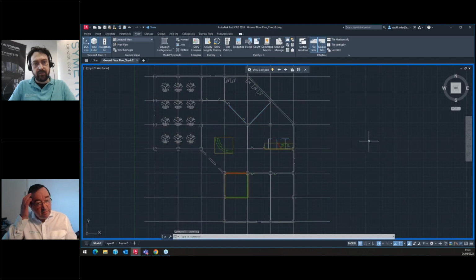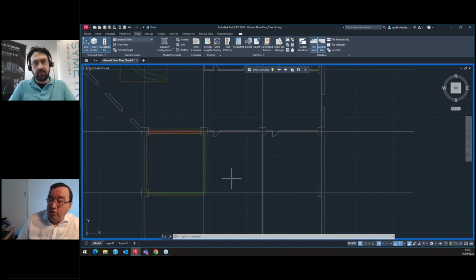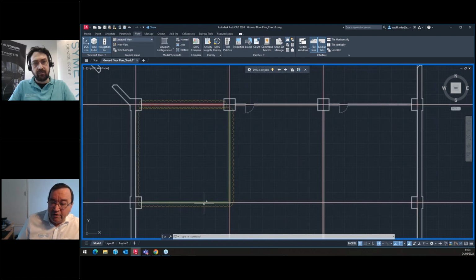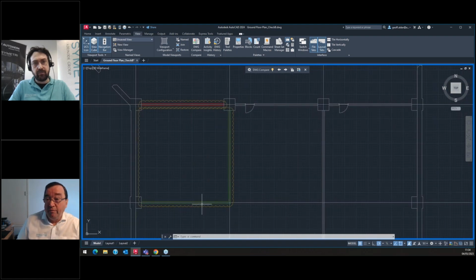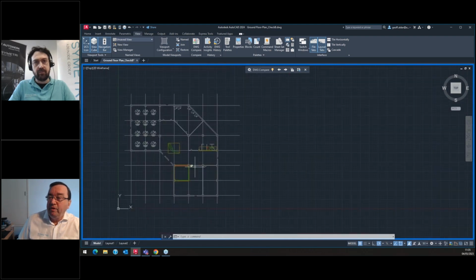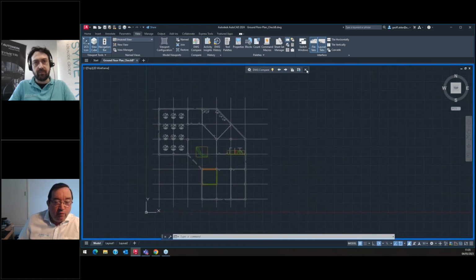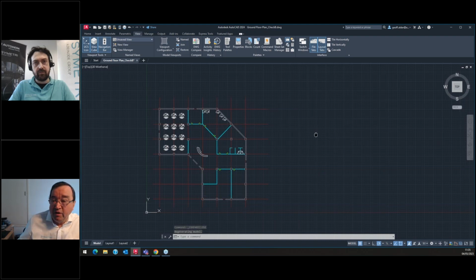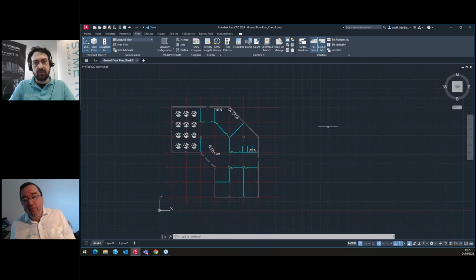And you can see that this drawing compare is flagging up a few places here, in this occasion, the interior wall has been changed from this one, which was the original one, to now being put around here. So drawing compare is actually quite a powerful tool in association with things like the traces. Like I said, in collaboration, a change is very apparent here, which is really useful.